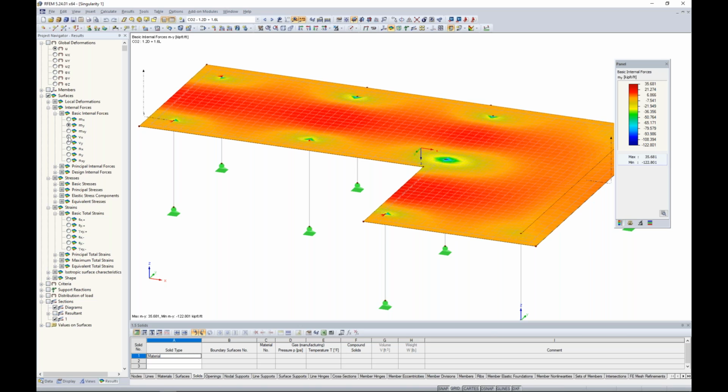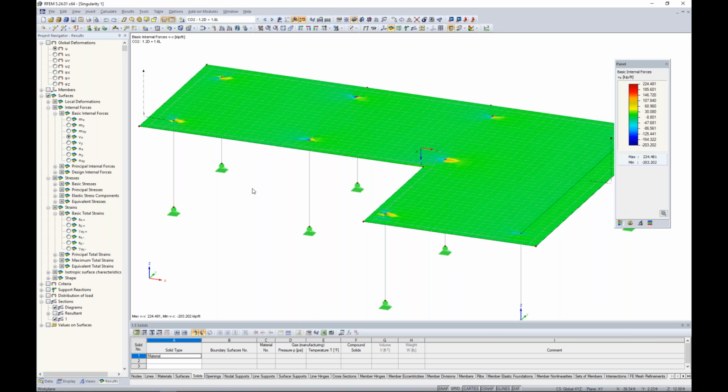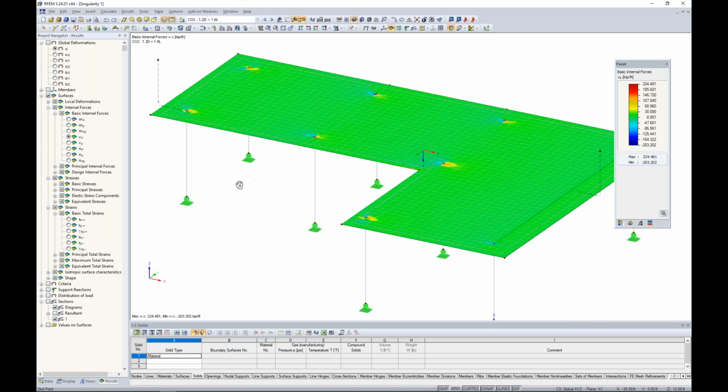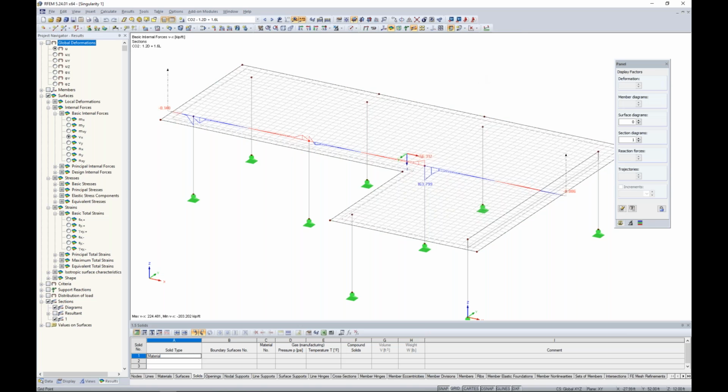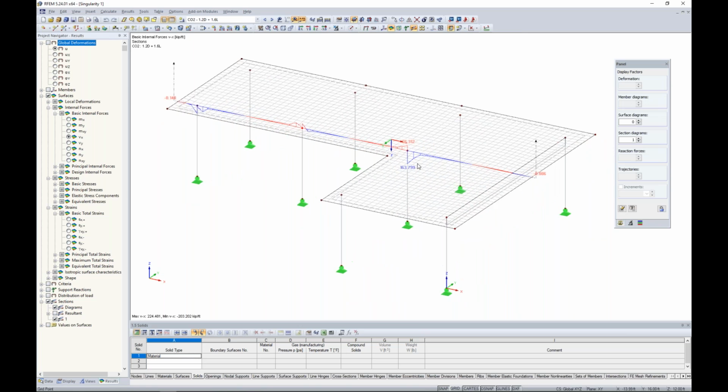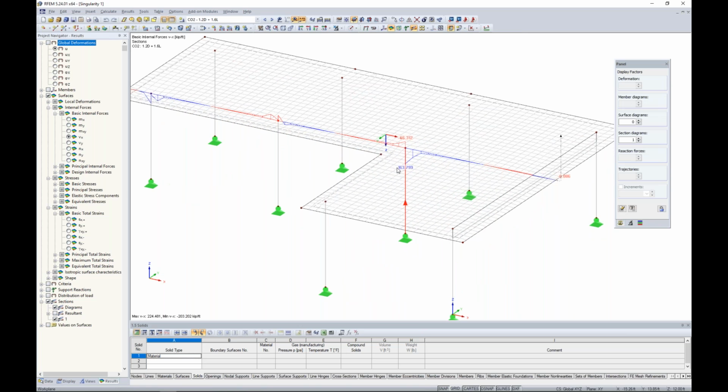And even more so can be said about the shear forces. Now, we fully expect shear forces to be higher at these column locations, but I've also made a section cut through my structure here that I'll go ahead and turn on, and maybe I turn off my ISO bands. And if we look at this section cut, you'll see that these shear forces are very high.